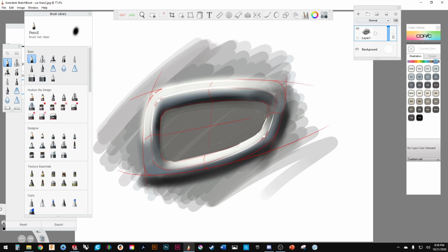I'll do it. So what we'll do next week, this model here is something that I would build edge to edge. I would create my profile lines, this outside boundary, this inside, this middle boundary, and then this inside boundary. And then I would create my contour lines to sculpt it versus trimming everything back. So I'll walk through, I'll continue with this base model here for trimming back and show you some of the advantages and disadvantages of that. And then we'll walk through this model, which will show you some advantages and disadvantages of doing what's, you know, edge to edge surface modeling.